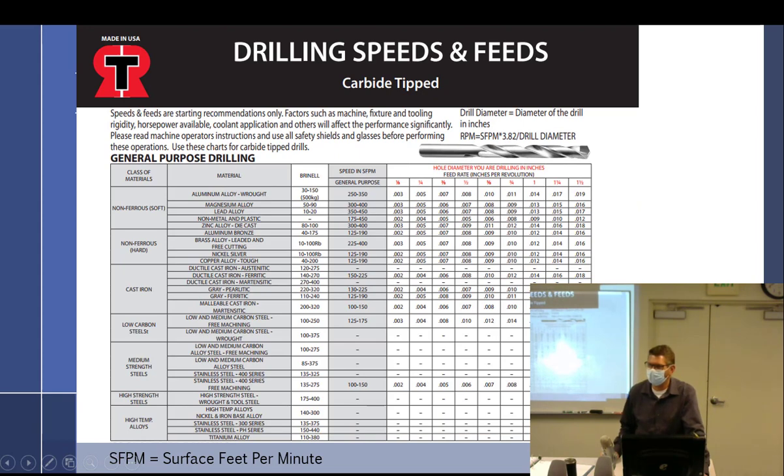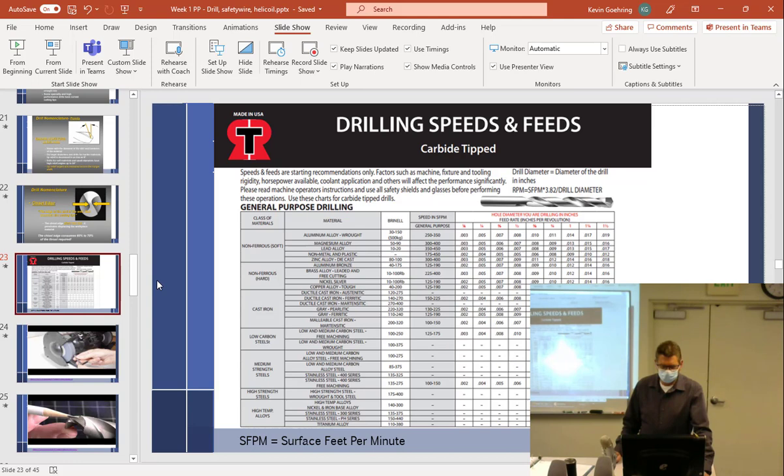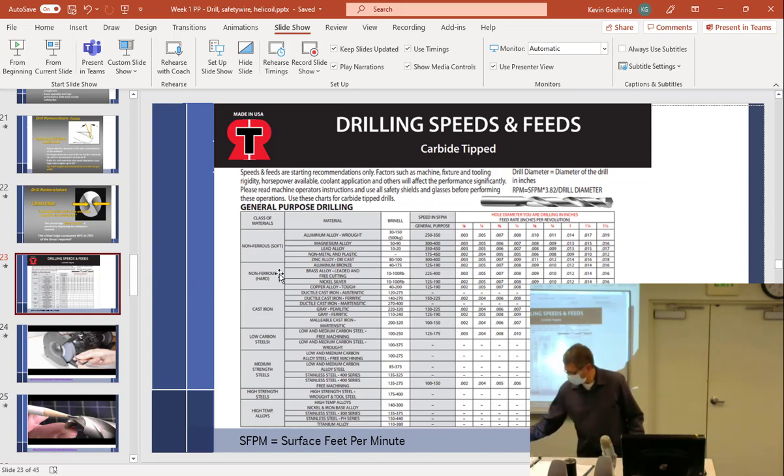What if you wanted to find out the hardness of the material? How would you do that, the Brinell hardness? I just get a hardness tester. There's that puts pressure on it? Yeah, I don't know. I don't think we have one here, but I had one at my shop when we used to do rocker arm grinding. You had to check the hardness of it. You just put it in a fixture and then you push down on it with a certain amount of pressure and it puts a little indent in it. It's not that big a deal. Okay. We covered that. I'm not going to belabor that point.